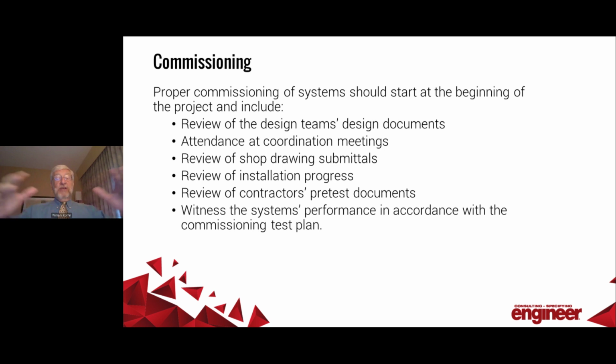So remember, the acceptance test protocol in NFPA 72 addresses the fire alarm side of things. If my sequence of operations says a smoke detector, heat detector, or radiant energy detector is supposed to do something, in addition to sending an alarm signal, it's going to have some control functions. NFPA 72 tests the fire alarm portion of that, so we test to the relay or the control module. Commissioning is end-to-end testing, where I make sure those elevators recall, or whatever is supposed to happen when that initiating device